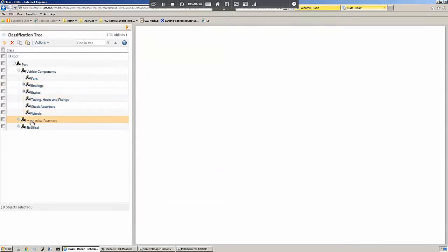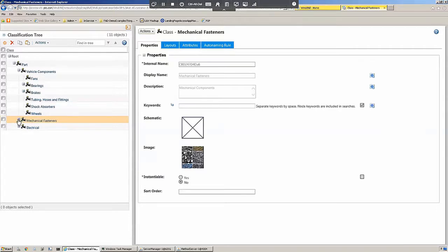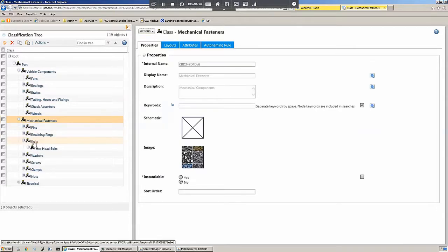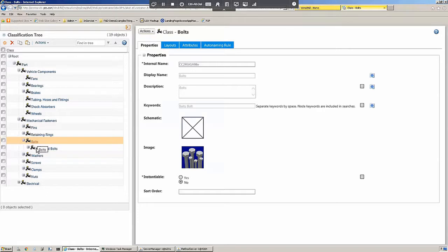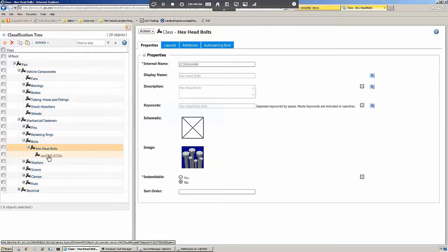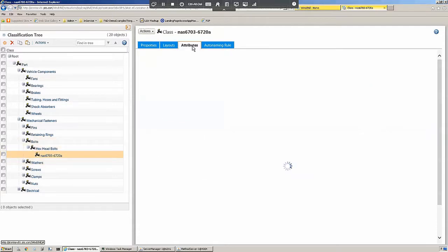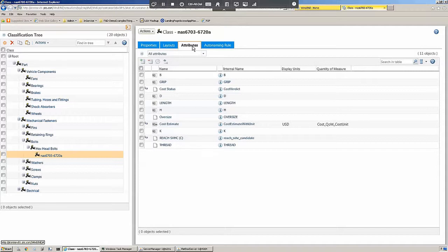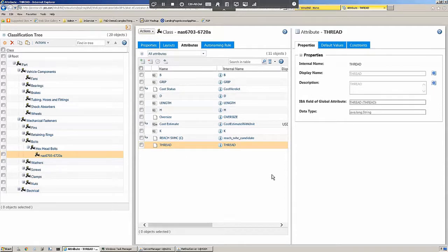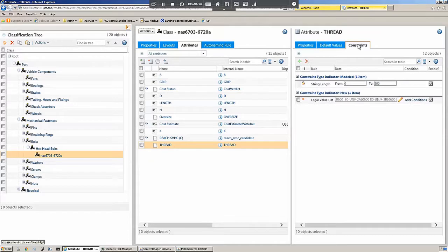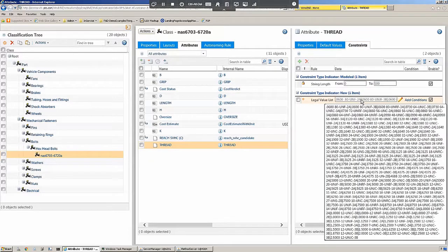Note the list of attributes are the same ones I used in the virtual catalog during my search. This lightweight attribution mechanism is how parts are classified with a common attribute set. During classification of a part, selection of a node in this classification hierarchy determines which attributes are added to a part's metadata. If a part needs to be reclassified, then simply changing the part classification attribute, which points to a different node in the schema, adds a different set of attributes to the part.